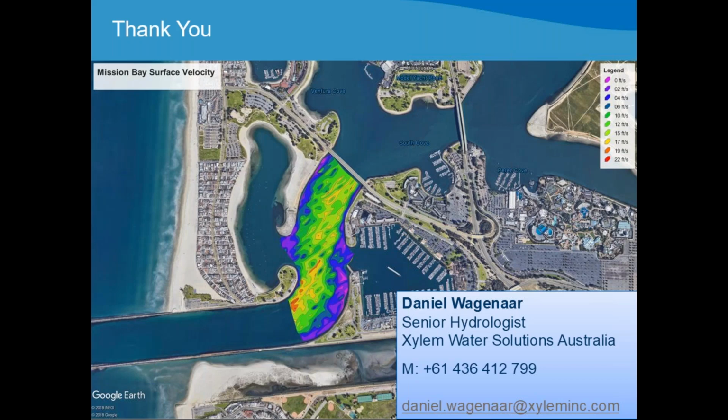Okay, thank you, Daniel. Next, if we have greater water velocity, say greater than 4 meters per second, would the 16 centimeter blanking distance be sufficient, or should we set a larger blanking distance based on observations at that time? No, the 16 centimeter blanking distance should be sufficient for that.